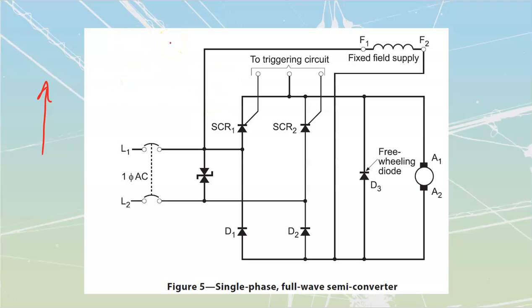My actual components themselves are going to pass values of AC and DC through. We'll start with the diode over here. You should be familiar with the fact that this part up here, the line, is called the cathode. The other one's called the anode because it looks like the top part of an A over there. This one will pass a negative through to down here, so that's going to be my negative side. This over here would be my positive side. If I take a look at my field winding, I see that my field winding is connected across from here up to there. So it's only partially connected through here.